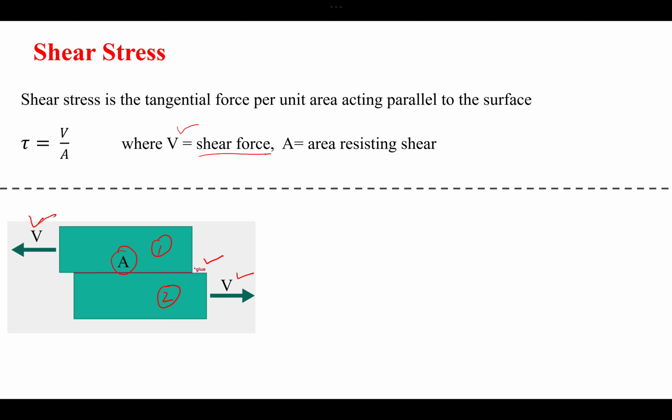Our stress in this case would be slightly different, in the sense that now the forces are applied to this contact region and are trying to slide one area over the other. Those forces are actually parallel to that contact region, and when the forces are parallel instead of perpendicular, we have the shear stress induced.